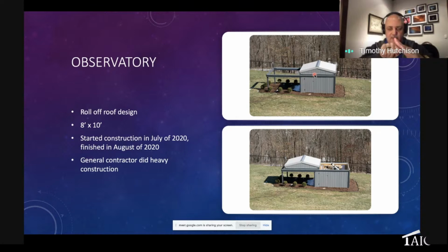And under that peak, what I did was I took something called a heat wire. Heat wire is used to keep your pipes from freezing, and you kind of wrap it around your pipe. And again, it automatically activates when the temperature gets too cold. But I took that heat wire and I ran it up through that V groove all the way up. So as soon as it gets cold enough, that turns on, and it keeps the observatory ice free.